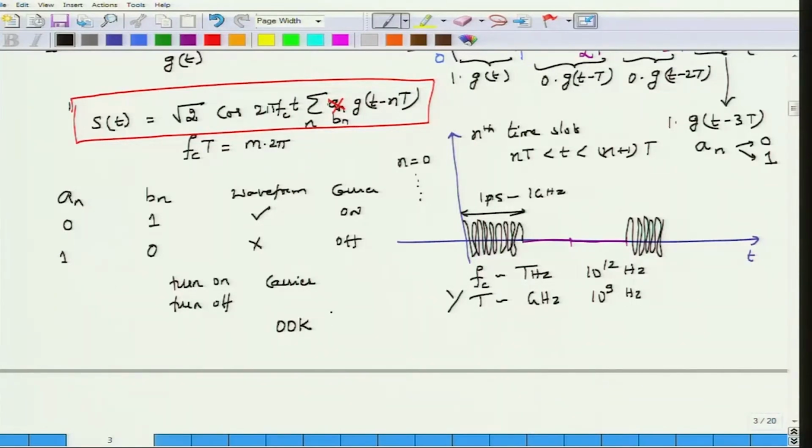Because this amplitude is the one which is shifted, this kind of modulation is also called amplitude shift keying. The keying should tell you the key kind of thing, like a piano. So you press that key down, you are connecting the switch, and the carrier is connected to the output line. You remove your hand from the key, the switch is disconnected and the carrier is turned off from the connection to the output line. So this is the so called on off keying or amplitude shift keying modulation format.